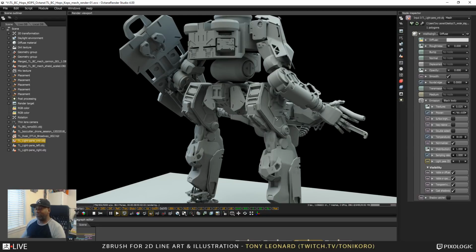But he also has an additional tool called KitOps, which I've done a few inserts from. So to create secondary and tertiary detail, I will place those inserts on, and it almost acts like a mesh fusion kind of tool, where it actually affects the topology of the face, and brings some complexity from kit bash cutters that you would have.